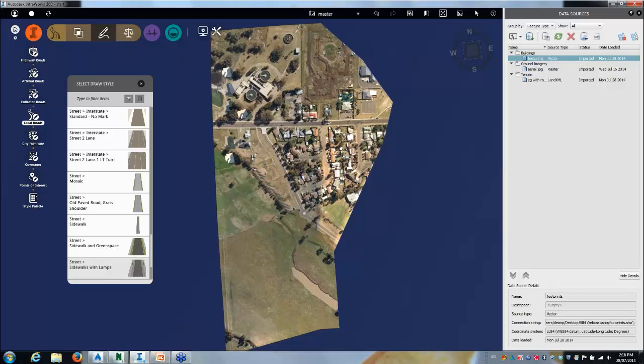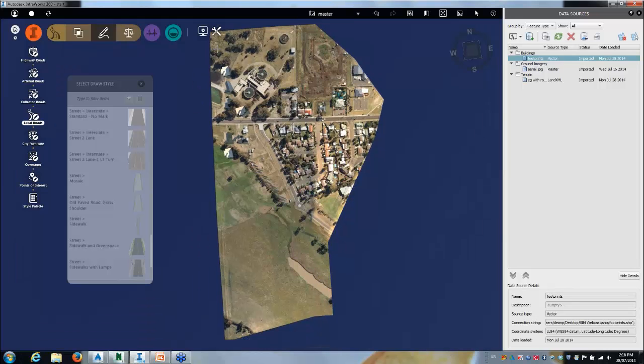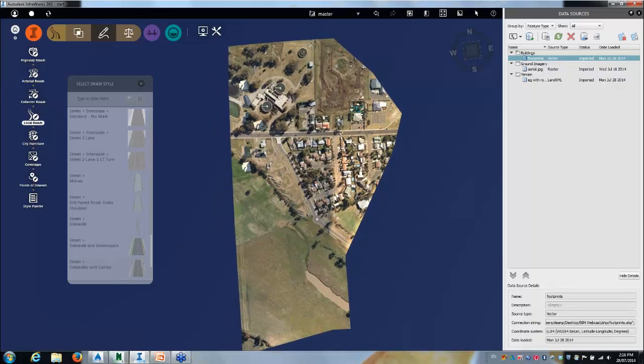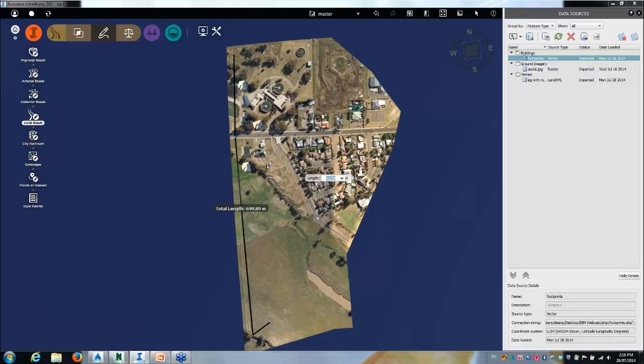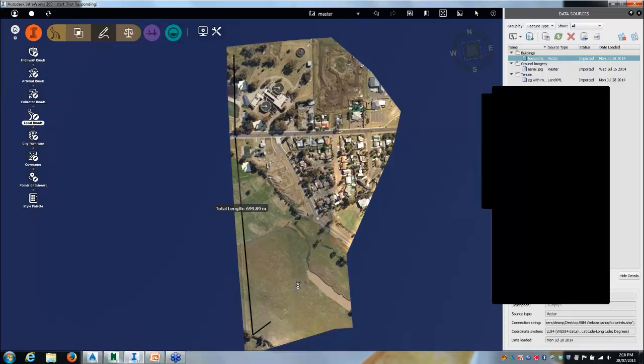And where I want to click it on, let's start up the top here, run it down to here, and you can see it's putting a little circular curve in there. It's using some design rules in the background there, so I'm just going to put a little kink at that point and run it down to about here somewhere. Once I'm finished, I go end draw. And what you get in the InfraWorks 360 is this has those design curves being laid out according to the design rules in the background, and we can also look at the profile of it.